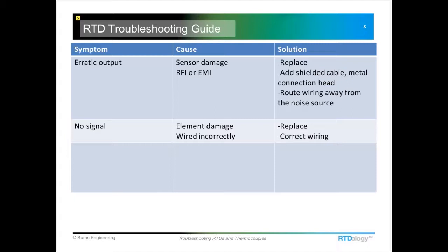The only solution for that is to go ahead and replace the probe. There typically is no repair to an RTD. The second cause of this would be radio frequency or electromagnetic interference. Could be there's a big electric motor nearby.